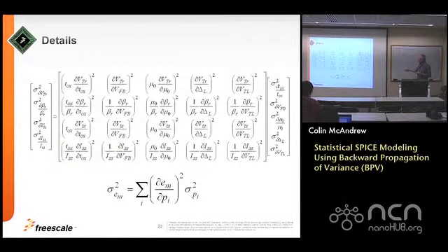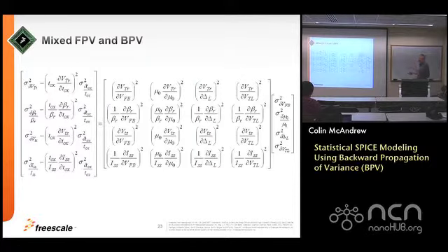You'll notice that there's 4 of these, and there's 5 of these. And the reason for that is that often there's a separate test structure for TOX, so we actually do typically directly get a measurement for that. And then what I can do is by multiplying that by the appropriate column in that matrix and moving it to the left-hand side, I can subtract that variance off from the measured variances or specified. Remember, there's specified variances in these quantities, and that gives me a set of linear equations that I can solve for the sigmas that I want here.